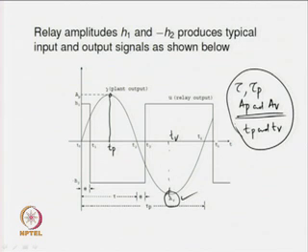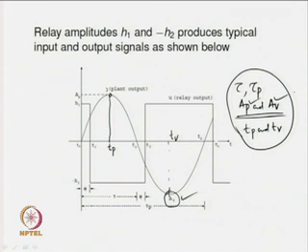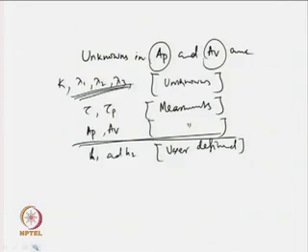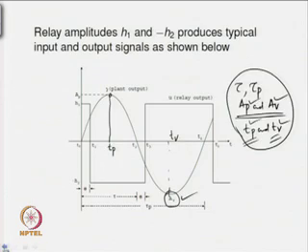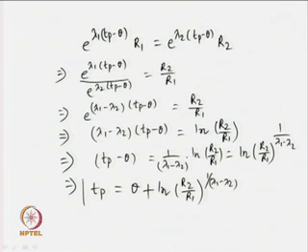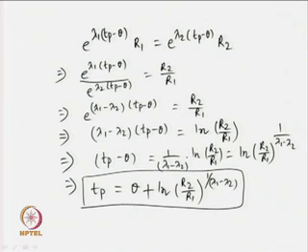It is up to the user: if it is difficult to find solutions for the set of nonlinear equations, instead of using the nonlinear equations for A p and A v, one can make use of the expressions for T p and T v by making measurements of the peak times and using the expressions for T p and T v. What are those expressions? We have already shown the expression for T p, which involves another unknown associated with the transfer function model, the dead time.